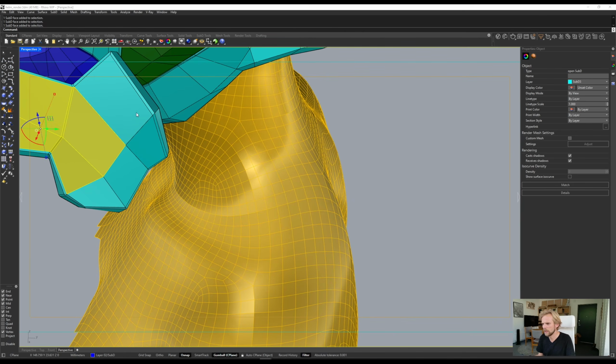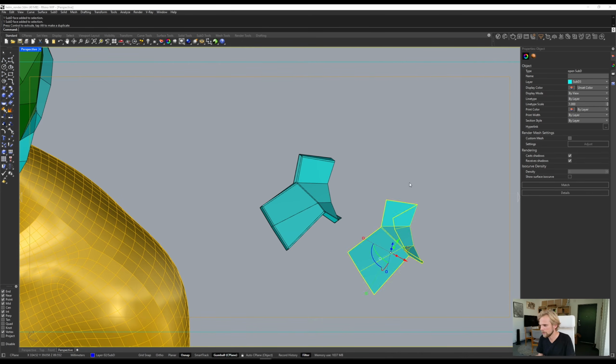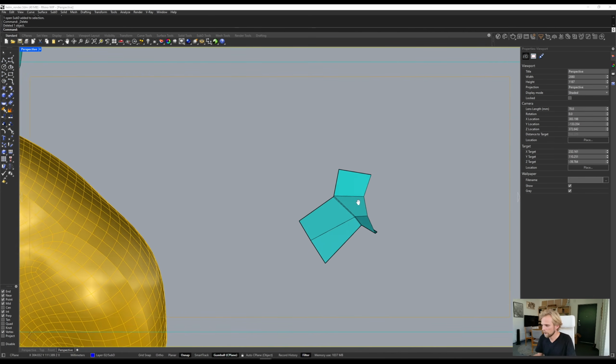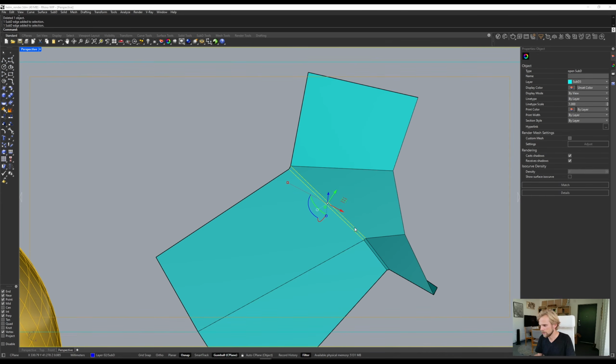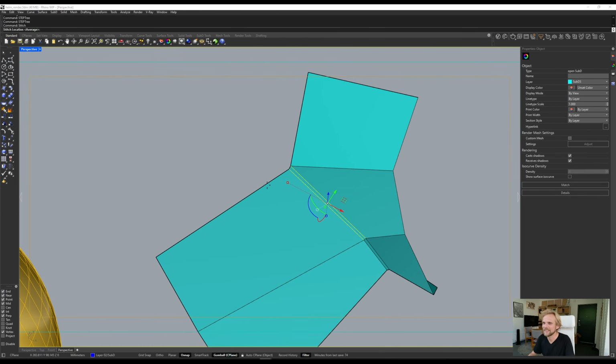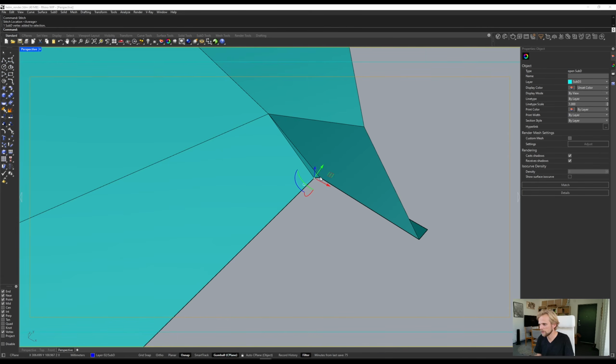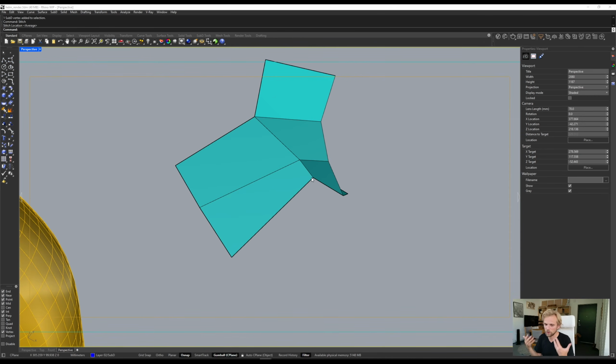So I'm just going to grab some polygons from here because the form doesn't really matter that much, like that. And also let's just stitch. So stitch, not step 3, stitch. Stitch basically forces two vertices, 2 points, or 2 edges together. And you can select the edges or the vertices with Ctrl-Shift clicking, right? So Ctrl-Shift click to select a point, stitch, to stitch them into one point. That's very useful for cleanup.